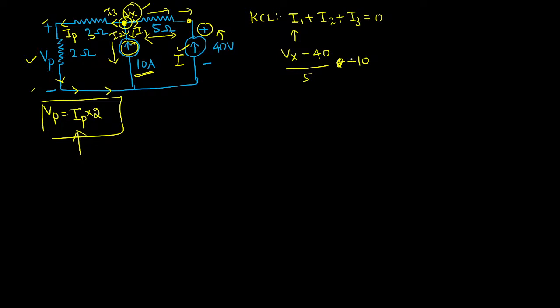When you apply nodal analysis, if you are finding any current in the opposite direction to the nodal assumption, then you have to reverse the polarity. Plus, how will you write I3? I3 is the current flowing through this branch.